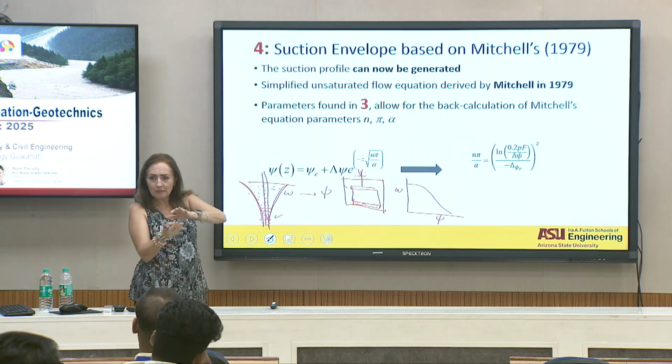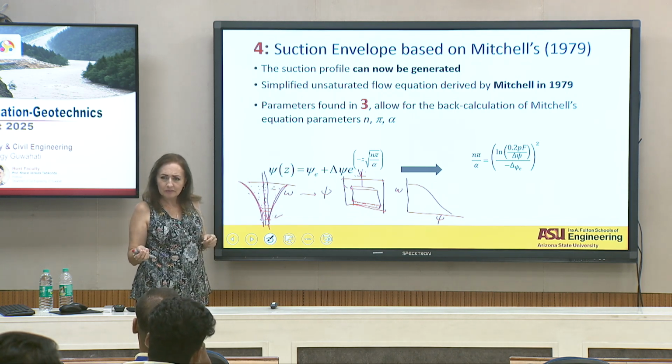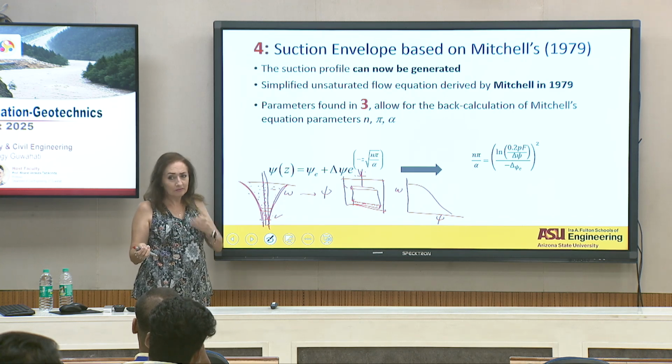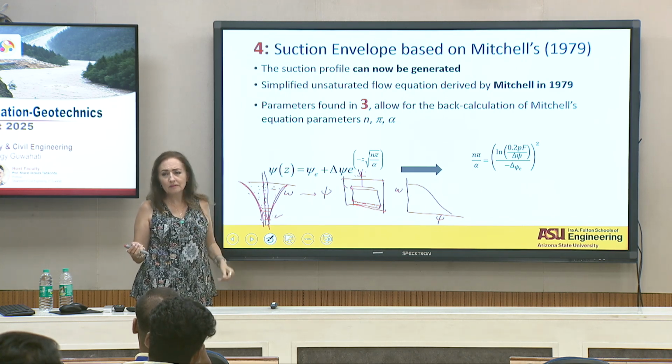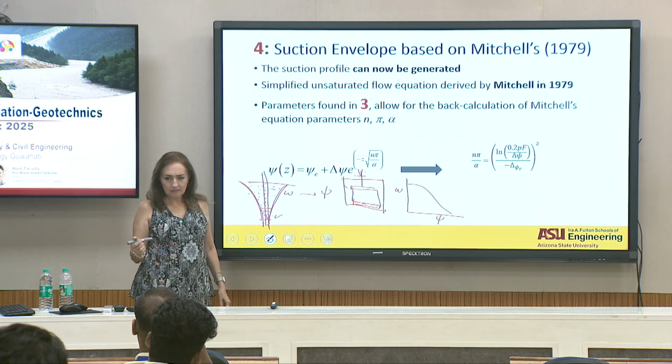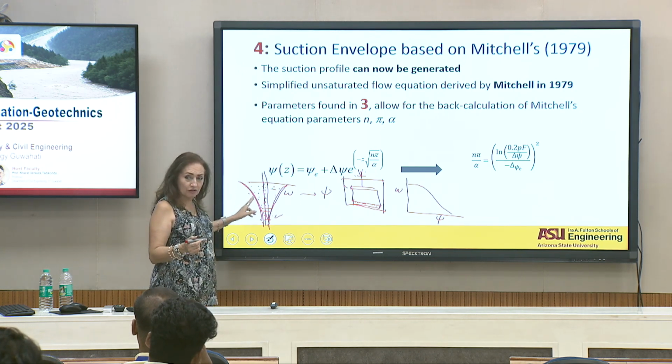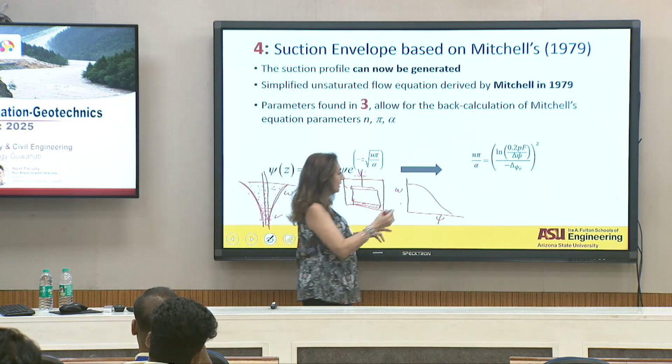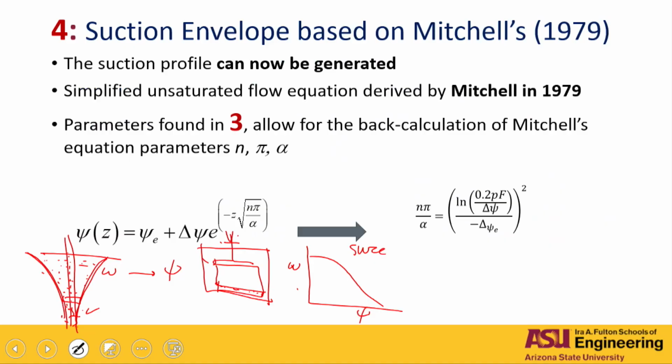My point is when you are trying to get all the suction profile there, as you are going deeper, overburden stress is changing. Yes. So I just wanted to know from the lab, when you are going to the suction, the field is at the moisture content. Yes. So we measured the moisture content, took it to the laboratory for the SWCC on that sample, and loaded it to the overburden pressure that we got at that point.